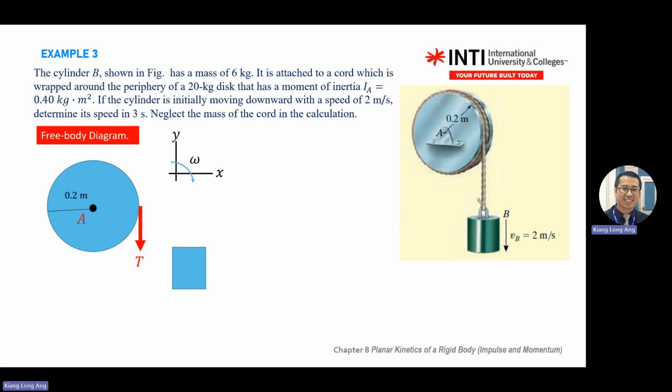There's a force pulling down. Again, the free body diagram refers to the target object. Don't refer to the wrong object. So there's a capital W again. Don't substitute mg first. Write capital W. You can write at the side capital W equal to mg, but don't substitute the value first. Then you write the connecting point at A.